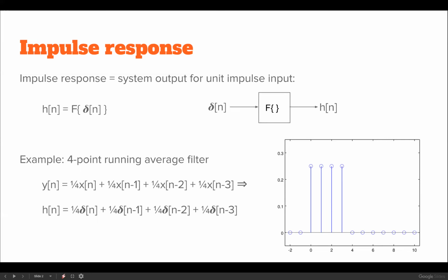Okay, actually that's also the trick when you start looking at whether the system is a finite impulse or infinite impulse response system. You basically have to look only at the values after the highest order delay.